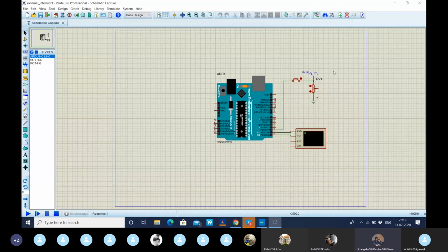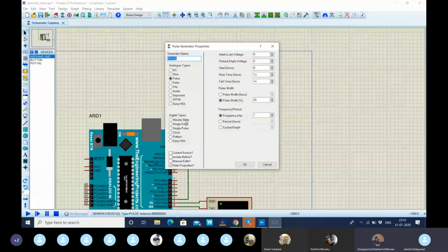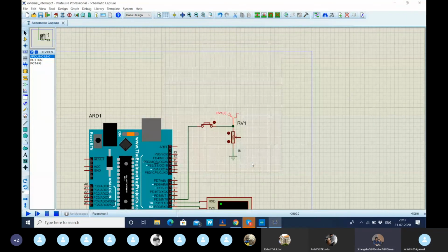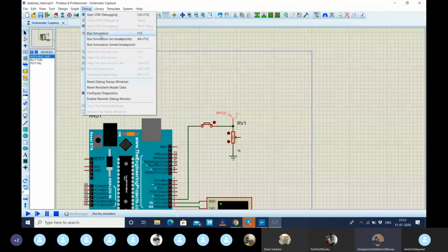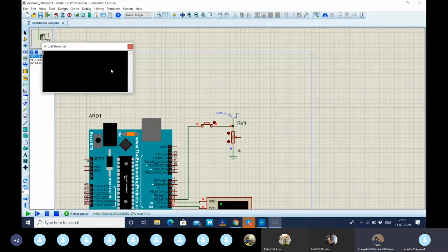This is the purpose of the external hardware interrupt. But if you want to measure the sawtooth wave, you can do it very well using the ADC, because slow, continuous changes can be caught. This is the way.